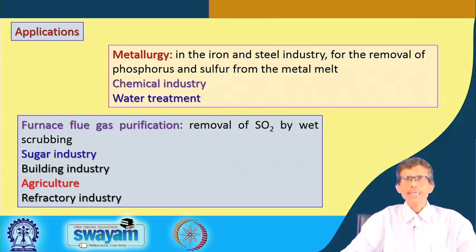This technique is known as wet scrubbing, that means in the presence of water you take out the sulfur dioxide by a base treatment. You get different sulphite salts as well as sulphate salts from that recovery. This recovery process from the different furnaces, because a huge amount of those gases is coming out, is a very important area of understanding as well as research, because you cannot leave all the gases to the environment, as environmental restrictions will be there.